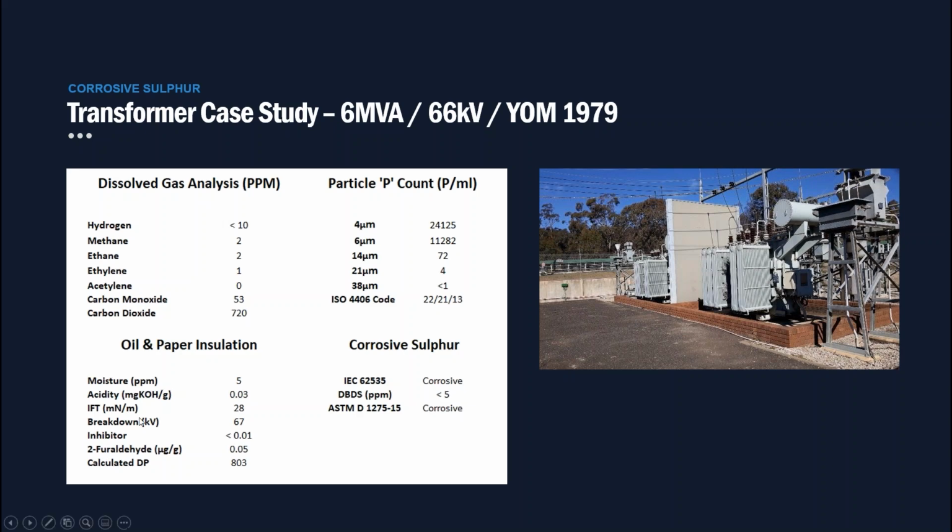So the particle count results were quite interesting. These came back showing high levels of contamination in the oil, which indicates abnormal operating conditions. So we had the oil transformer resampled, and the retest results came back with a big improvement in the particle count results. So we think there must have been a lot of material in the sampling valve, and it needed a second flush to clear the drain valve. So we'll monitor the particle levels when we resample the transformer in the future.